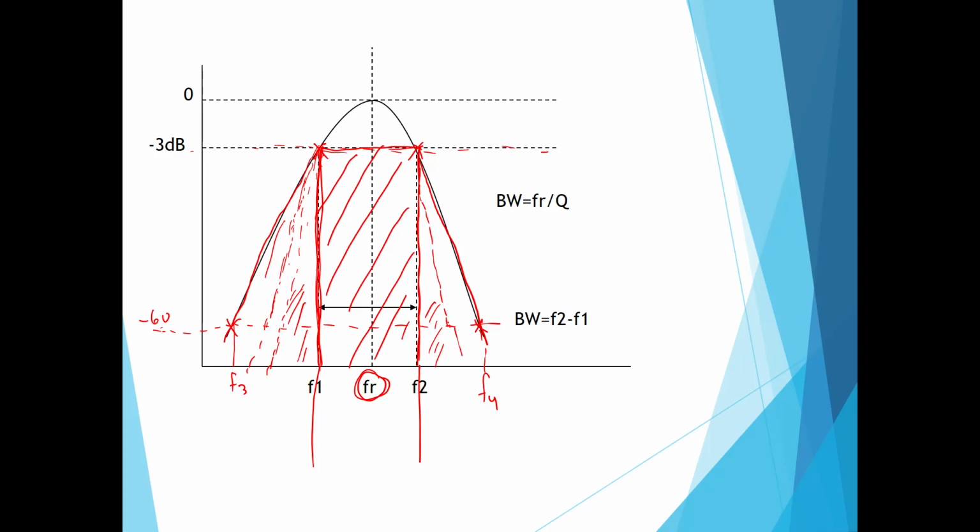Ideally, we cannot produce a filter that is very sharp like this, cut like that. It will have a skirt or a slope like that too, which will include small harmonics of signals. But that is insignificant, because if you have a very steep slope, the amplitude of the harmonics in the skirt will be smaller.